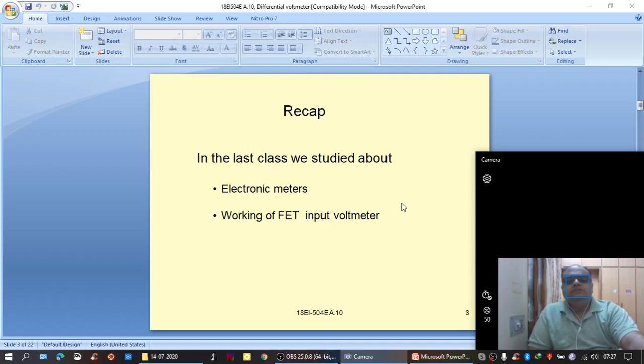FET EVM is one such electronic voltmeter offering very high input impedance, making use of a range attenuator circuit, that is a potential divider circuit, in combination with a single pole 3-terminal range select switch, called the range selector circuit, with an FET and a BJT and a bridge network consisting of one BJT and three resistors, out of which one is a potentiometer used for zero adjustment.